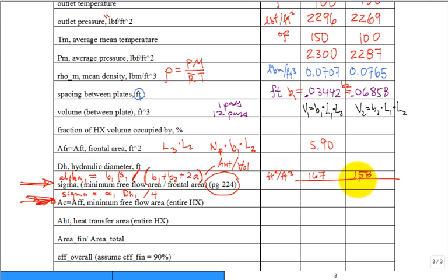And then the sigma, which is the ratio of the two areas, that's what I wanted to get to, is 0.2904 and 0.600. So around 30% and around 60%. Think about it. As fluid 1 approaches, that whole cross-sectional area has to get down into 29%. That's the free flow area divided by the total frontal area. But the other one, for fluid 2, has 60%.